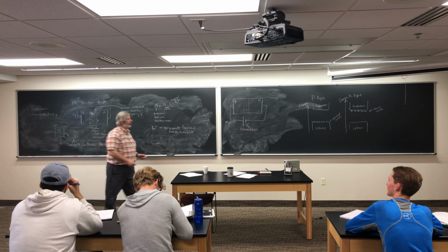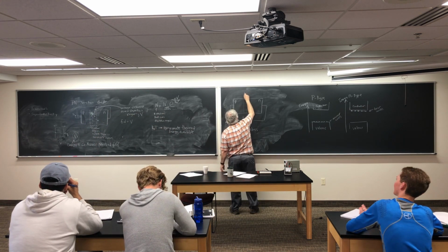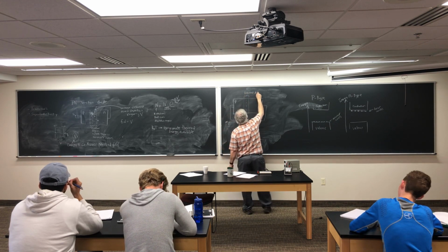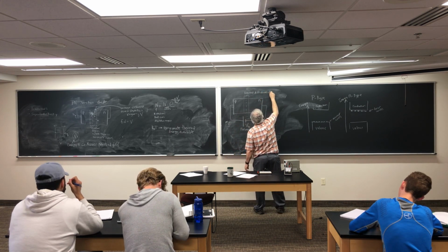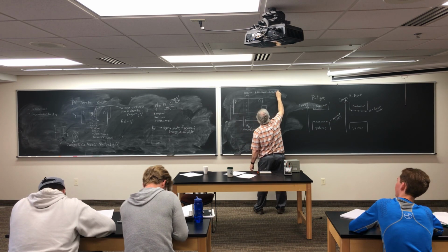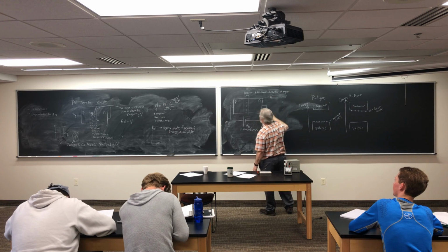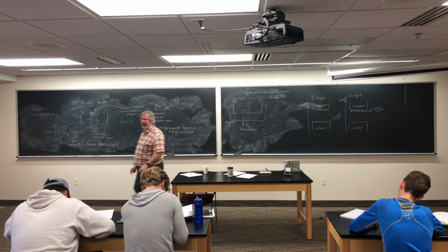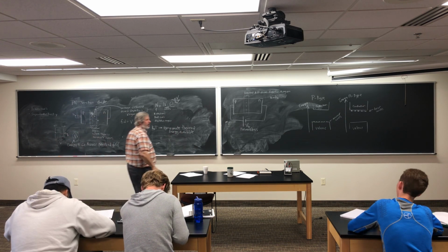what you're really doing is reducing that potential difference across there. So the potential difference across this junction, across this depletion region, would be what you had before, minus this bias voltage you put across there, right?